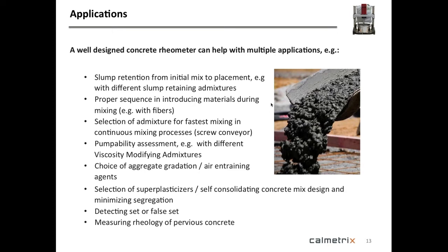For example, as I mentioned just now, you could look at slump retention from initial mix all the way to placement. If I want to try different slump retaining admixtures, the SRAs, or if I'm an admixture company that wants to develop those, I would use the rheometer to look at their effectiveness. I would be able to compare them, look at different dosages, and look at the effect of different mixing methods, different speeds of mixing, and different mixing energy on my slump retention.